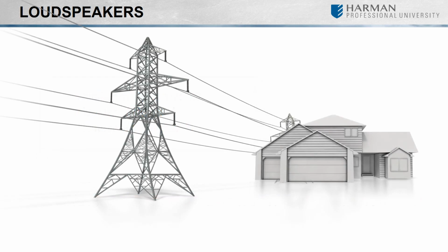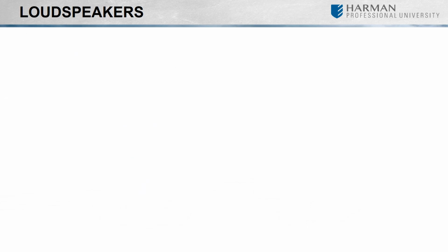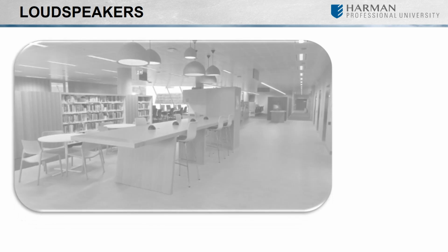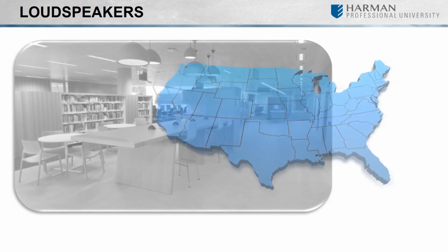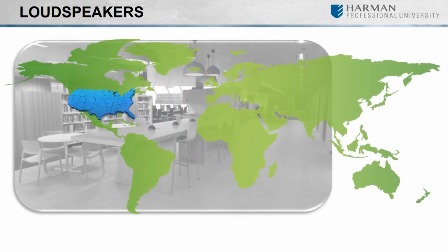Remember in the CSC video when we brought up a power company distributing power to everyone's home and likened that to amplifiers and speakers? At the time, it was to fill you in on why we were talking about wattage taps. We'll explore that idea some more. We have what are called distributed systems, also commonly known as 70-volt systems in the US, 100-volt systems outside the US, or high impedance systems.